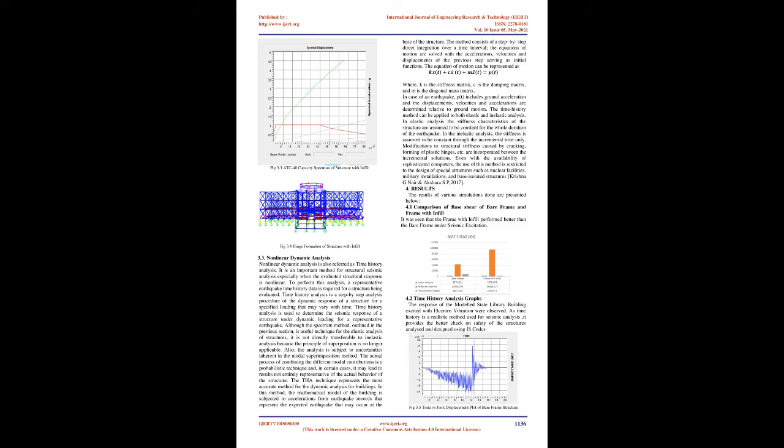Pushover analysis of buildings subjected to increasing lateral forces is carried out until the preset performance level, target displacement, is reached. The promise of performance-based seismic engineering, PBSE, is to produce structures with predictable seismic performance. The recent advent of performance-based design has brought the nonlinear static pushover analysis procedure to the forefront.